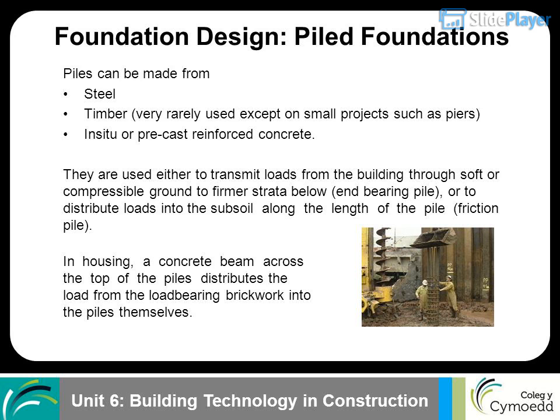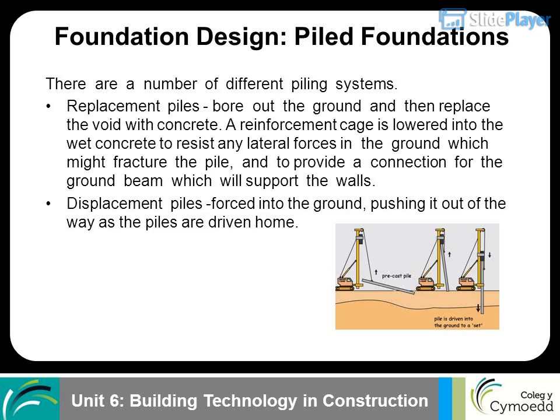Piles can be made from steel, timber (very rarely used except on small projects such as piers), or in situ or precast reinforced concrete. They are used either to transmit loads from the building through soft or compressible ground to firmer strata below, end-bearing pile, or to distribute loads into the subsoil along the length of the pile, friction pile. In housing, a concrete beam across the top of the piles distributes the load from the load-bearing brickwork into the piles themselves. Foundation design: piled foundations.